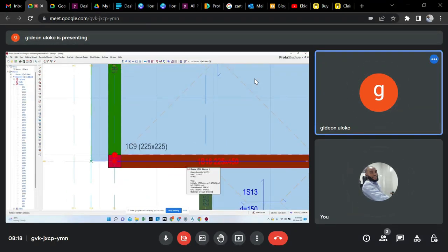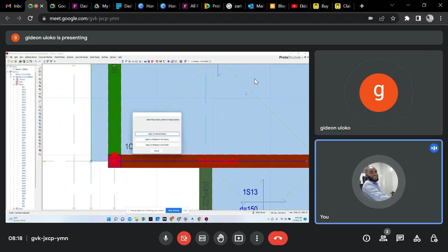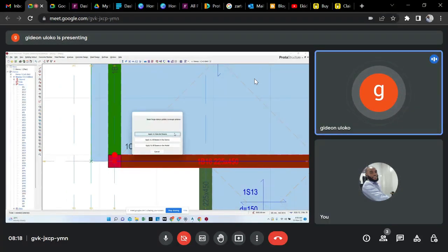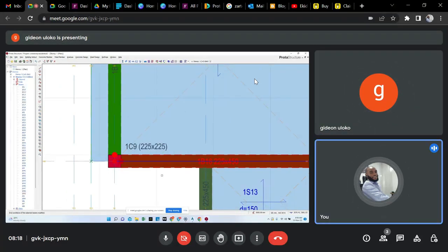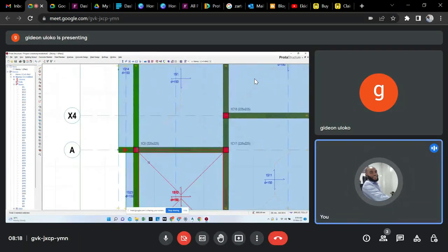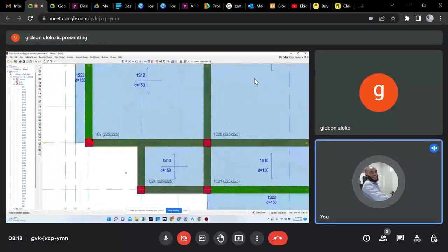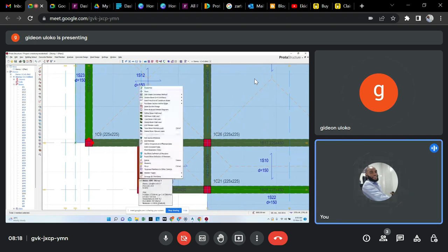Same thing at I because that's the left hand side. Yes, it's left. Now you can see the same thing. Now pan down a bit, let me see the bottom of that. Now stop. This beam, that's beam 41. Let's hinge that one. That will be both ends, because both of the ends are discontinuous, so they will be the both ends option.